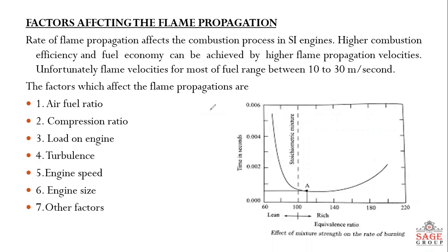There are several factors which affect our flame propagation, like air-fuel ratio, compression ratio, engine load, turbulence, engine speed, engine size, and other miscellaneous factors.